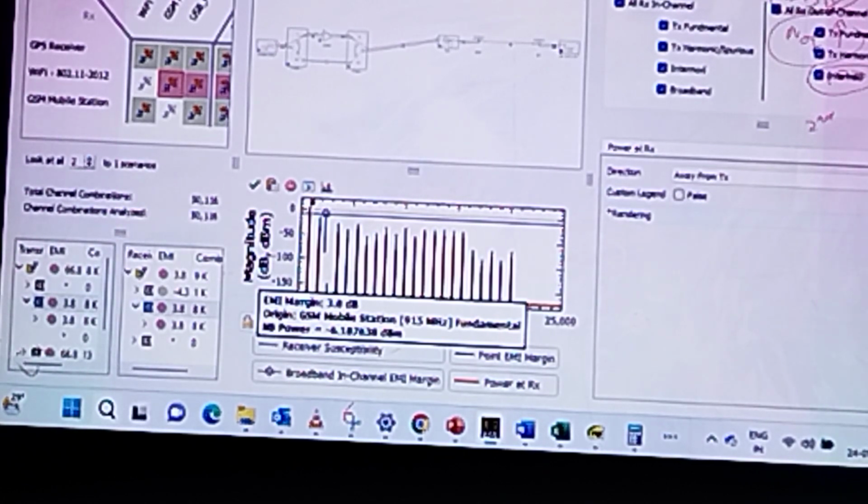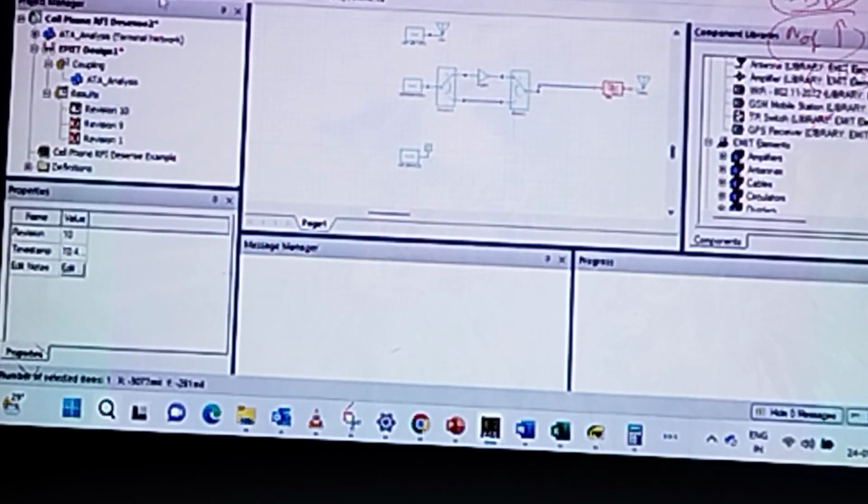Again, if you want to do any other things also, you can use these schematics like a divider or something. If you want to add it over here, you can play around with your circuit. Only the antenna model you will be taking from HFSS, and all the other schematic elements are implemented here. In your case, sir, you can design these kinds of filters already and we can input them here. Actually, for antenna filters, we don't have any kind of import option here as of now. Only with the antenna far field we can do that, because basically this is for RF interference.